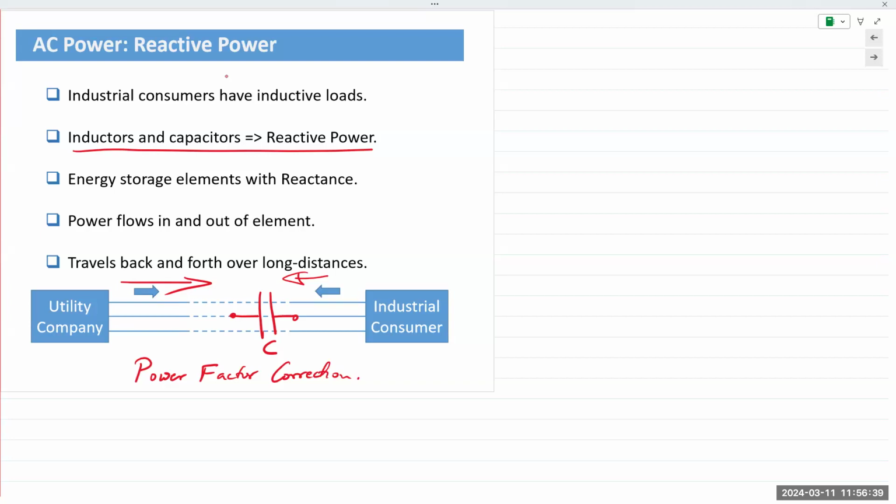The utility company would not supply all of that power. If power for the entire campus goes out, the places on campus that have huge electric machines have to work with the utility company to maintain a staggered turn-on for all of those electric machines. Otherwise, the utility company does not have the resources to supply all of that power.